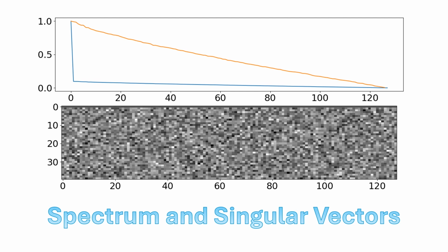So this is interesting, and from a compressive measurement theory point of view, making these kind of pseudo-random projections can be very useful in estimating the image with fewer measurements than one per pixel. So that could be a good idea, but later in chapter 8 we'll look at the actual feature structure of images, and the features are not distributed over the full extent of the image, so it makes more sense to do this kind of coding locally within an image, where you won't have this problem of such a very ill-posed